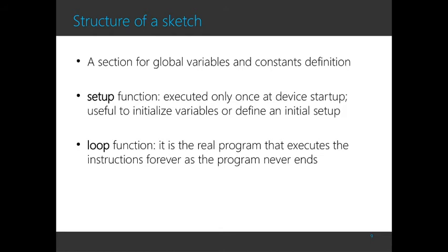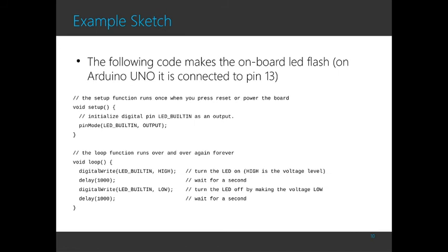One basic function is the setup function, and it's executed only once at the device startup, and it is useful for initializing the variables or defining an initial setup of pinout and so on. And the loop function is where the real program works, and it is an infinite loop that always keeps processing the instructions until the switch off of the device, because the program never ends.